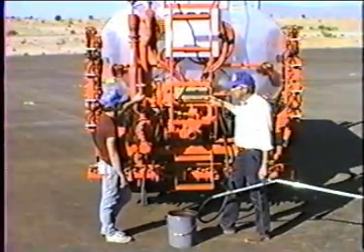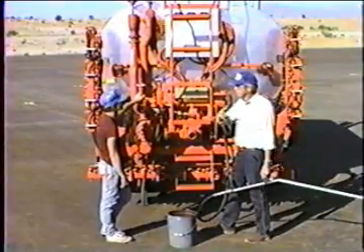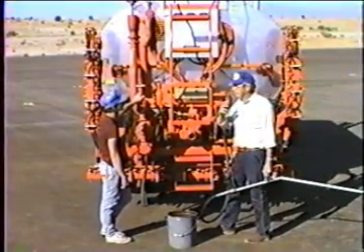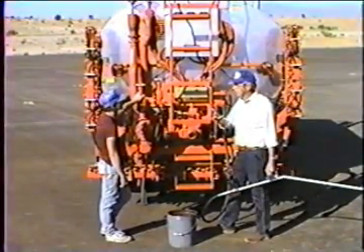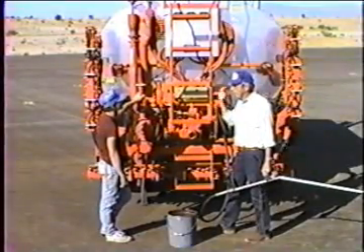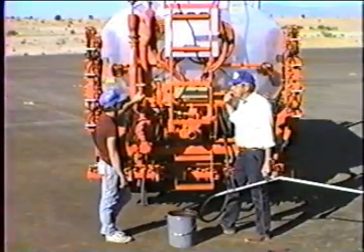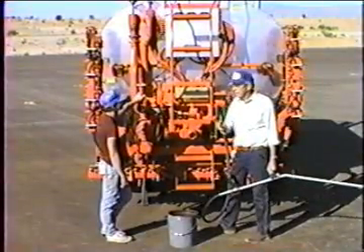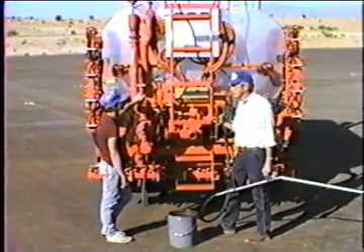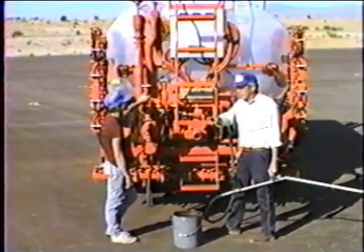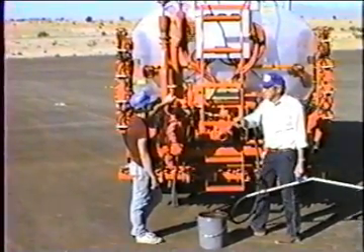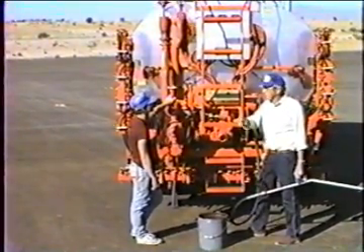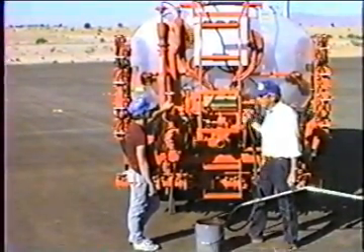If I went to the job with this truck and I pulled a trailer along with me, and I knew that this was a state of Oregon job and it's paving grade asphalt, I know they're going to test it. So the very first thing I'm going to do when I get there, I'm going to go get the inspector and I'm going to say, bring your sample cans. And I'm going to take him to my trailer and I'm going to get him samples of the asphalt, both one for the truck and for the trailer, out of that trailer valve.